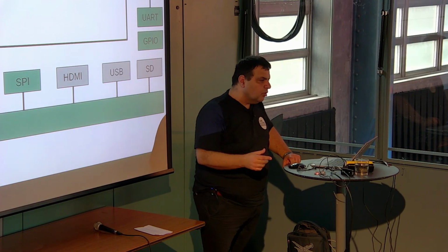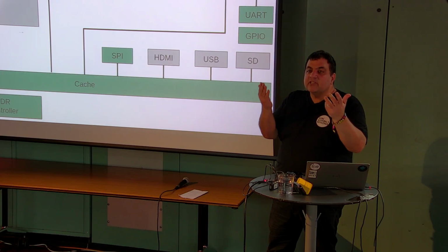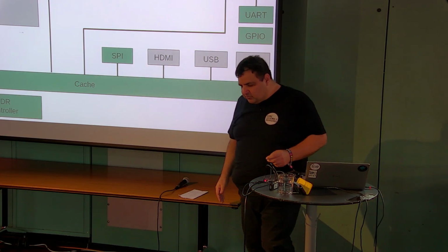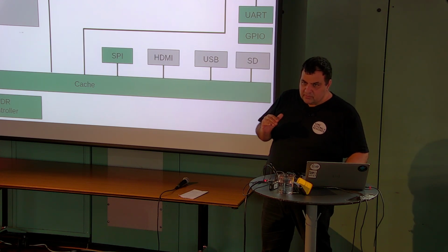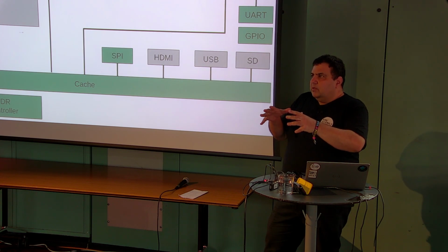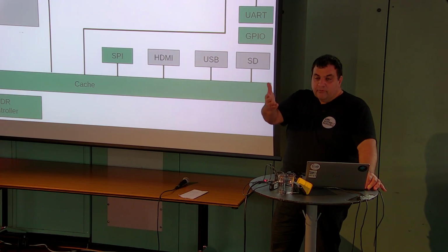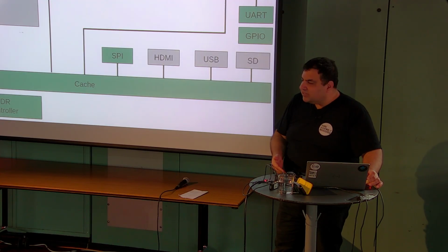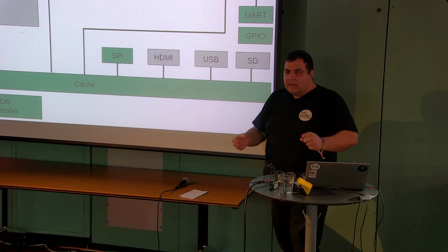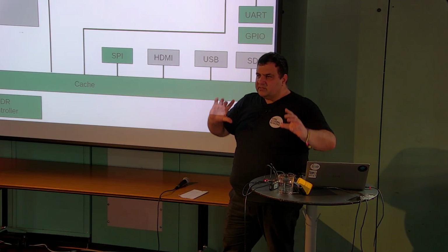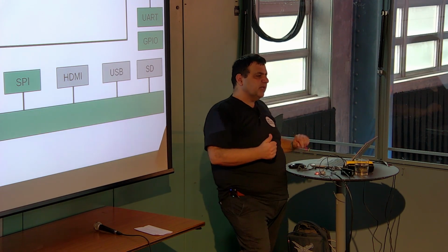The reason I didn't go with a hybrid FPGA CPU chip is cost. They're expensive. If you start with, I want the bill of material to be lower than $80, then a lot of those things that people in our community do all the time, because they're great, they save you a lot of time, they mean that you don't spend 4.5 years on a project and still only have text mode. But if you're looking at it as I want the end product to be cheap, then they don't get you over the finish line.